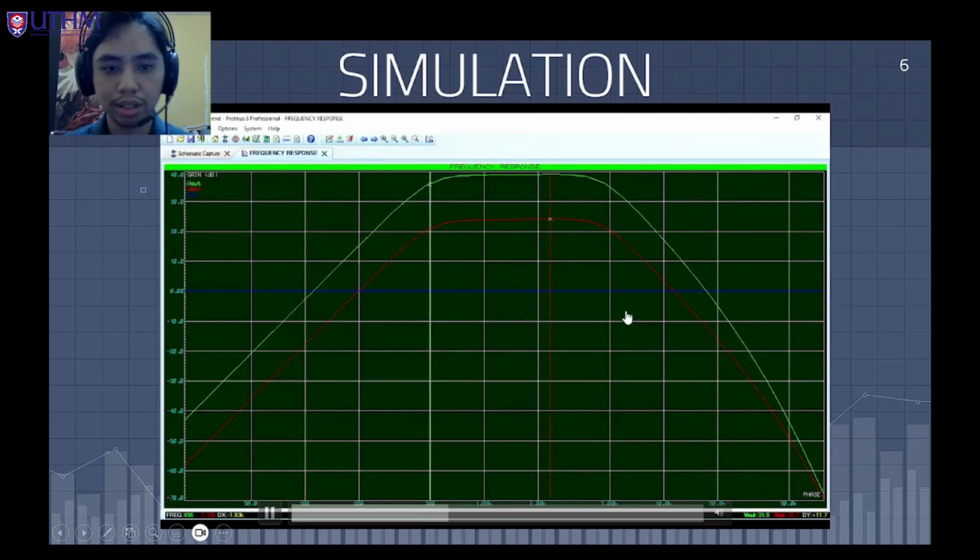At the breakpoint gain, which is at 36.1 because of negative 3, we can see that the frequency becomes 511, very close to the 500 Hz that we needed in the spec. Let's see the other side. For the 36.1 decibel breakpoint on the other side, we get 4.69 thousand Hz, very close to the 5000 Hz, only short of 300 Hz.